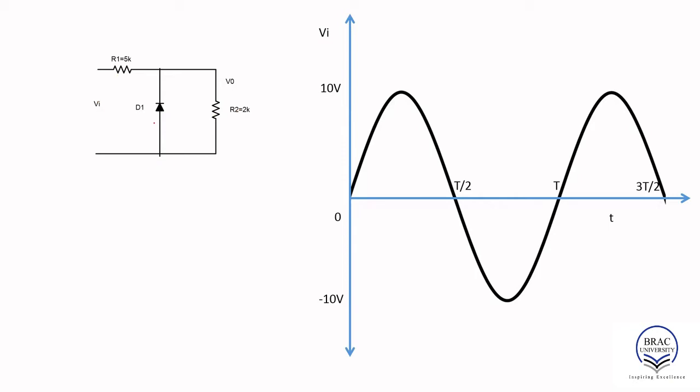Okay. So also notice the orientation of the diode D1 is in the upward direction. So that means if you keep the signal to my left, it is in anti-clockwise direction. So in that case as well, the steps we are going to follow are very similar to the steps that we followed for diode AC analysis for half wave rectifier and for full wave rectifier. So that means we're going to apply the same steps. First of all, we're going to determine the transition state voltage for that circuit.